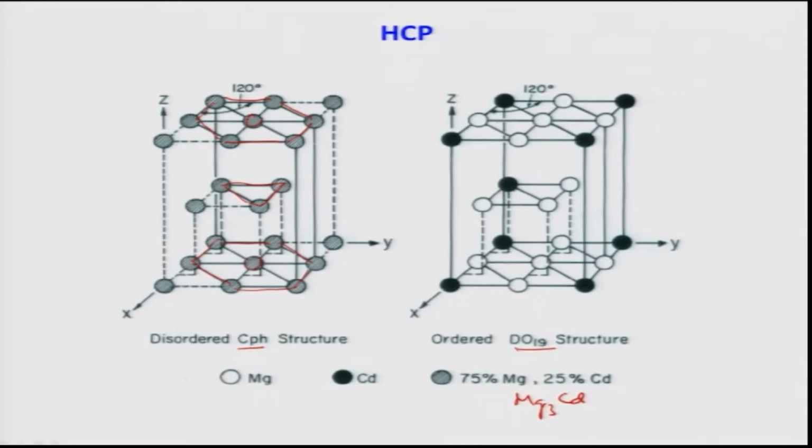and in hexagonal unit cells they contribute 1/6. So, it is basically 4/6, that is 2/3, and this one is 1/3. So, 2/3 plus 1/3 is basically 1, and then the rest are contributing to magnesium. So, 1, 2, 3, 4 and 1, 2, 3, 4 by 1/6, that means 4 plus 4 is 8, 8/6, that then becomes 4/3, and then you have 2, 2 each, so half, so this becomes 3 atoms, okay. That is how the calculation can be done.